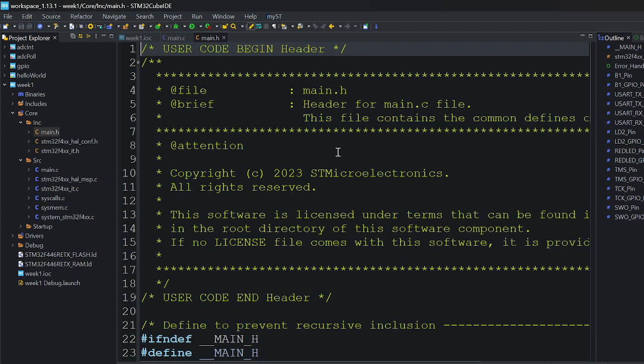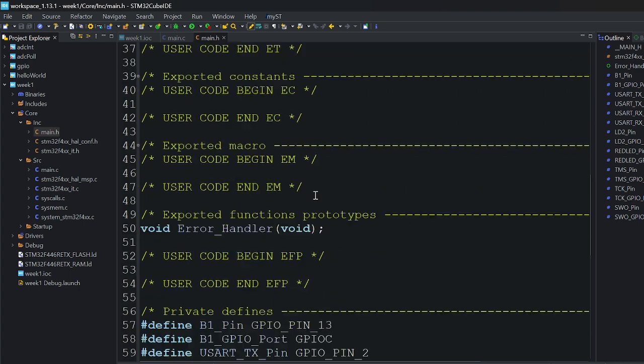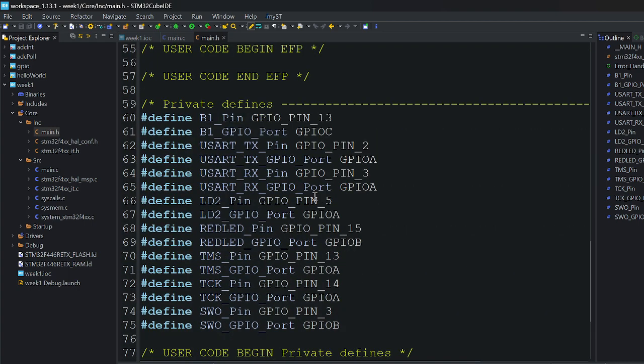Okay, so here we scroll down through, and I said red lead, so there's red lead right here. Red lead is GPIO pin 15, and we looked last day, GPIO pin 15 was 0x, it highlighted pin 15. That was the only one in the 16 bits.